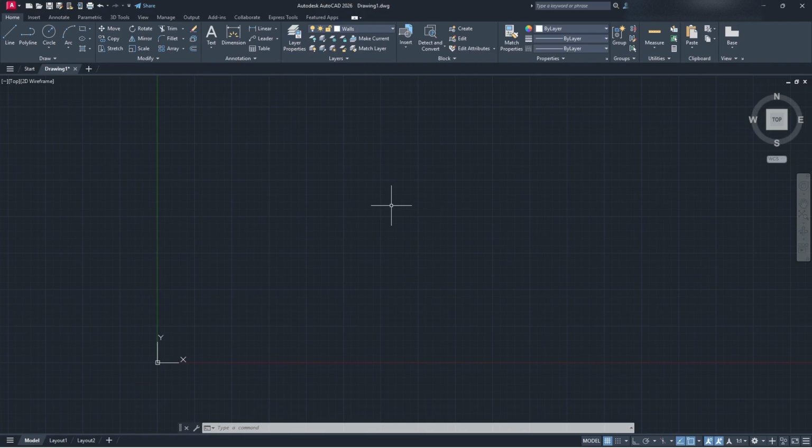And we're ready to start. So if you have guidelines already, make sure that you have your guidelines set out so you can start drawing and following along with us. If you don't have guidelines, you can just see what I'm doing, follow along. I don't have any guidelines set. I'm just doing this to give you a quick lesson on floor plans. So the first thing that you can do is you can either start with polylines or you can start with rectangles.